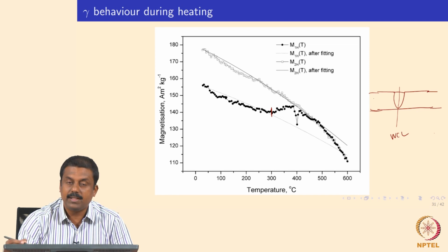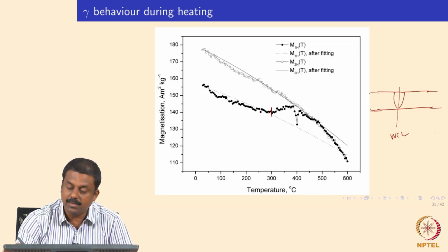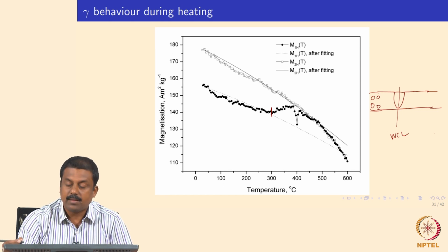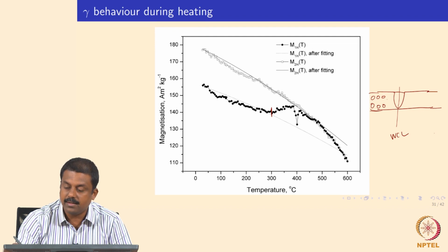If you want to measure the magnetic saturation, we need to take samples from the varying regions. For example, the base material, the subcritical heat affected zone, where temperature reaches below the critical intercritical temperature, the intercritical region, as well as the fine grained and the coarse grained heat affected zone.